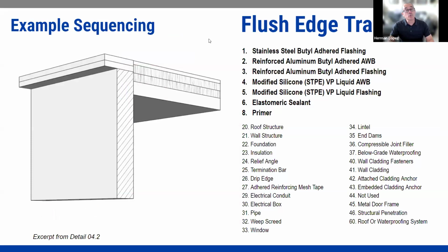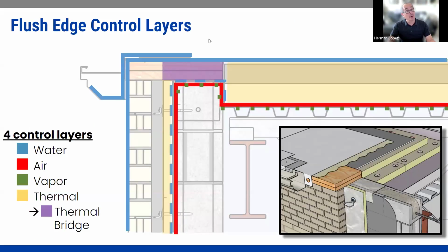All right, but continuous wetting and drying is going to degrade that wood prematurely. That's right, and so that's why you'll see the air barrier and the secondary water resistant barrier is below that wood. Had this material come up and wrapped around, it would now be on the pool side, if you will. And that's not an ideal place for the wood blocking in this scenario. You really want that separated from the pool. That's a good point, Herman.